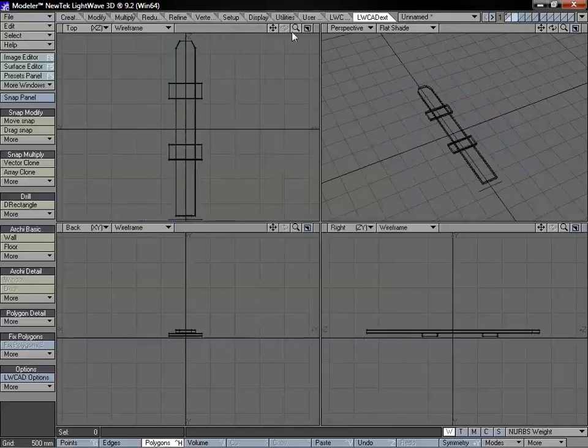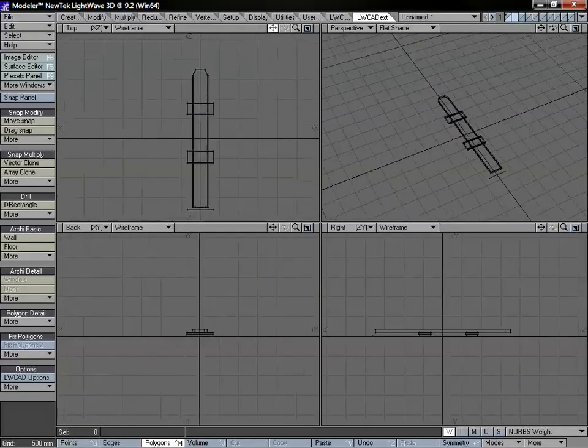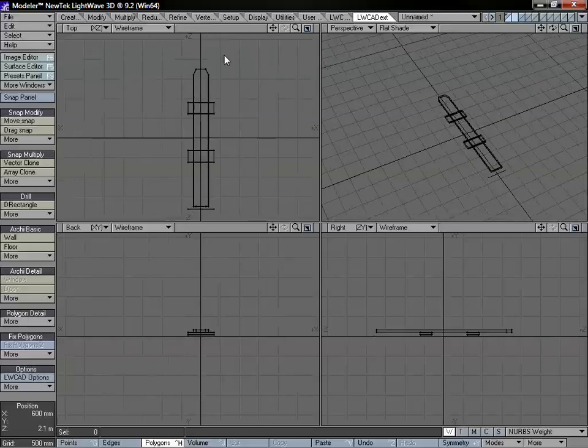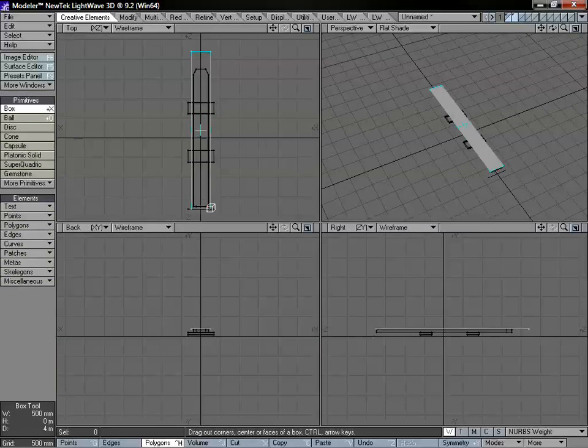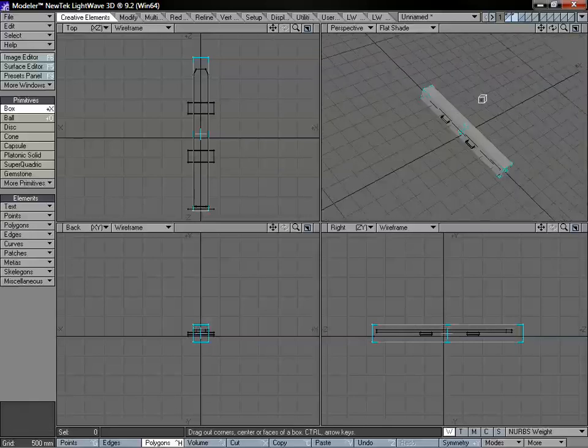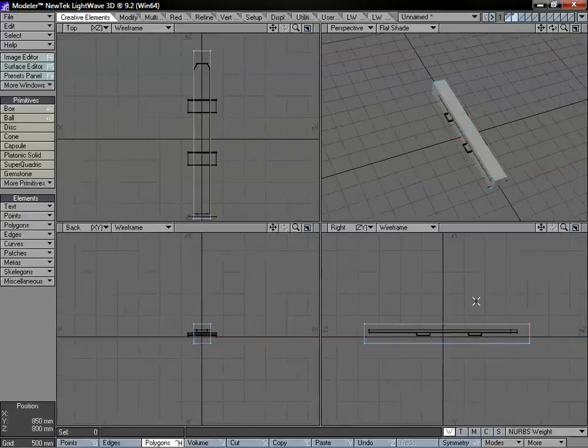Now we're going to keep this in a background layer and just design the area for our post. And one thing, a really good thing to do is just keep this in the background layer so you have a good idea of your size, because you do not want them to be different sizes, because it will remember the scale that you create them at. And if we have an object that is not proportionate to each other, then we'll end up with really large fence posts and small actual fence segments.